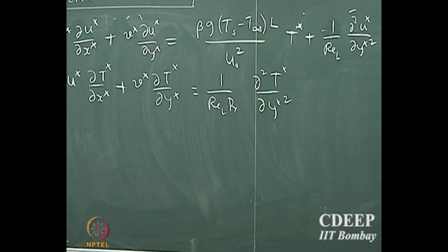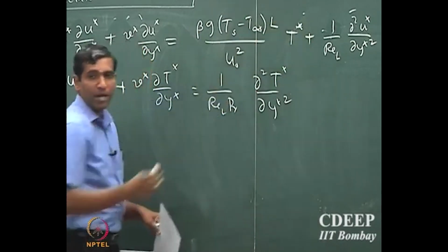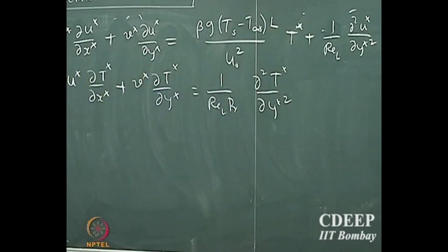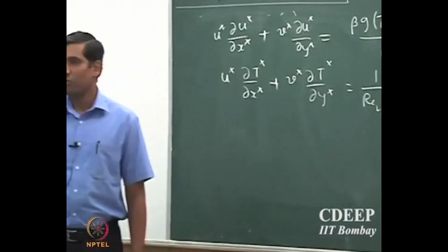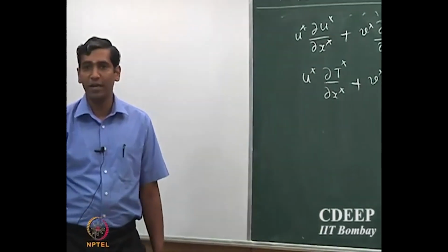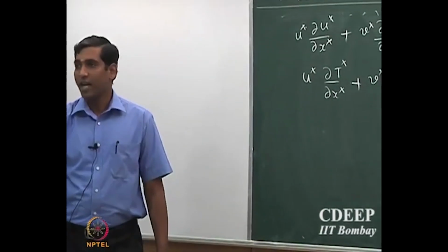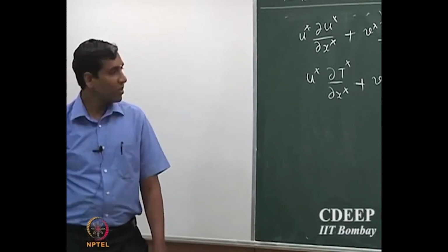They are not very different from what we saw in forced convection, except that you've got this new dependence of the velocity on the local temperature, and that's because of the density gradients, and that's because of the body force that we have included in the model equation. So now they are coupled. In the earlier case, the momentum balance and the concentration and temperature equations were decoupled, so we could solve the velocity profile independently of the temperature. We can't do that here.